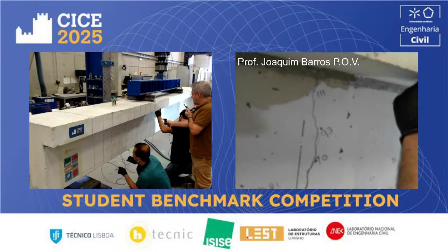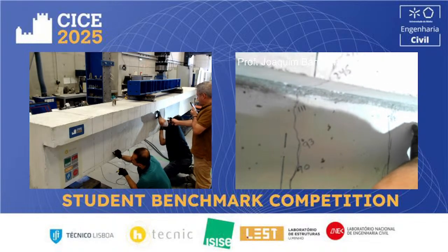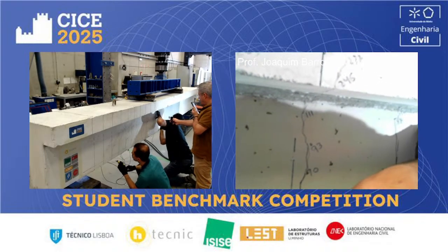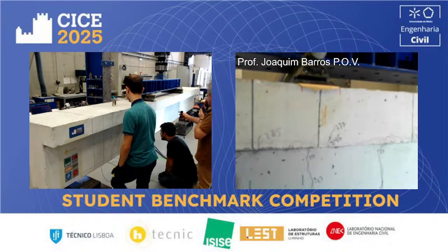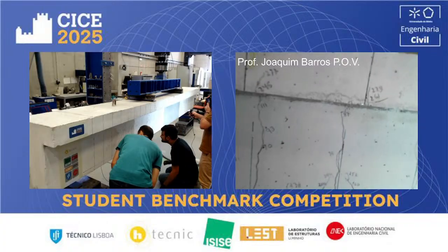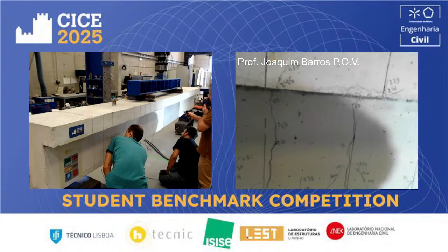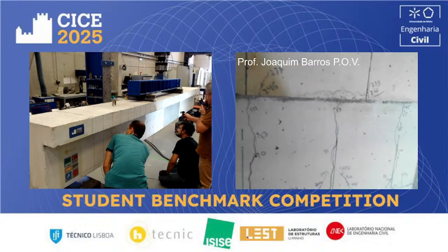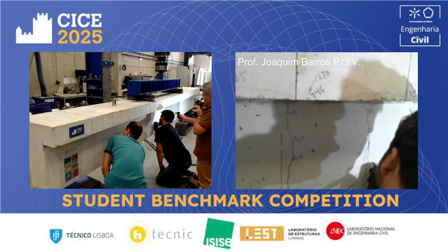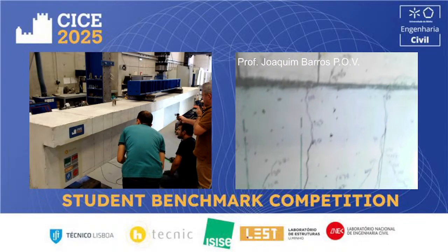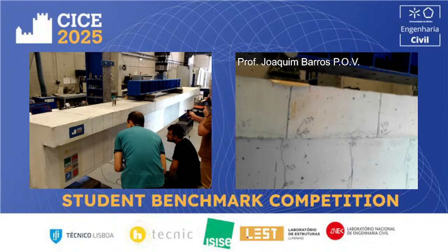The crack opening is increasing, 295, in the primary flexural cracks. It's quite visible now. I should remember that we don't have any horizontal reinforcement in the middle of the web, so we have it only in the bottom and in the flange.